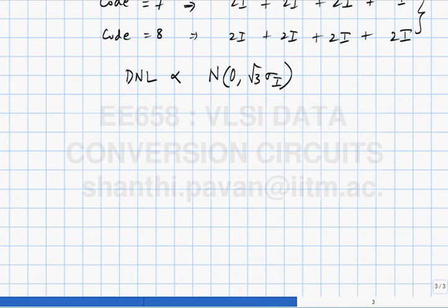If you know how much area your decoder adds, how many square microns of area you need to realize a certain number of gates, then you can figure out a segmentation which will give you the optimal area.